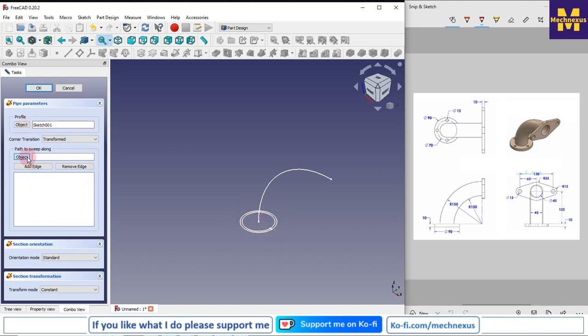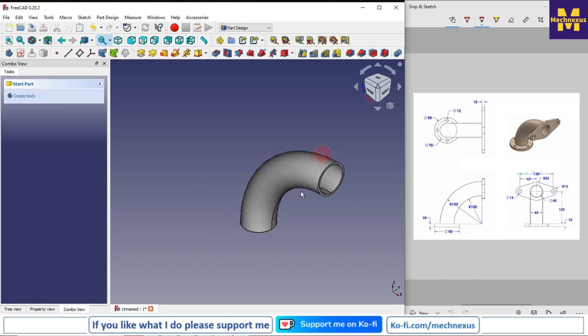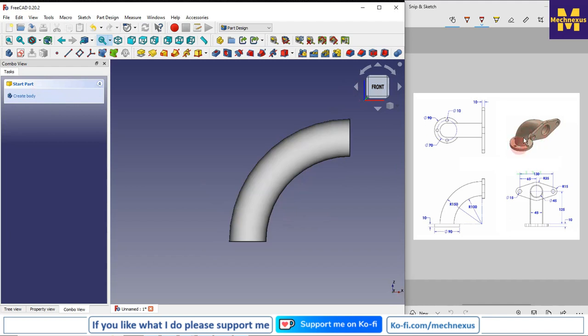Now select the path, and from here transformation mode is constant and multi-section, so we will select the constant, and we will keep it as standard, and I will say OK. So if I switch to the front view, we can see that we have made our base feature.